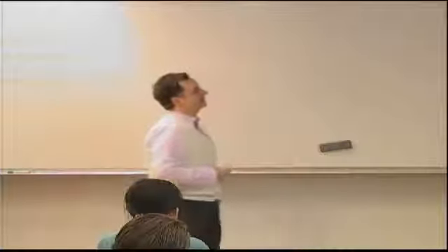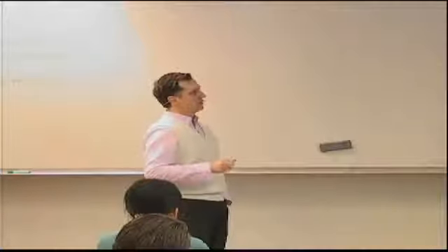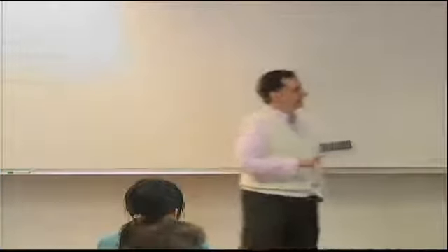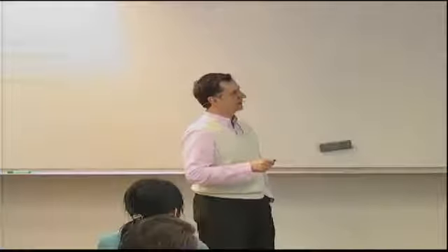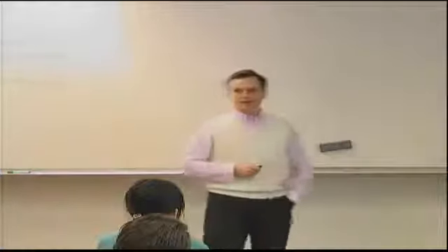Now, since I'm trying to calculate Nx, the compressive force at any x, y location in the plate, I need to remember my stress function F, which was this expression from 1 or 2 lectures ago. And the fact that the Nx then is given as the second derivative of this F with respect to y, which means my Nx will have this form.